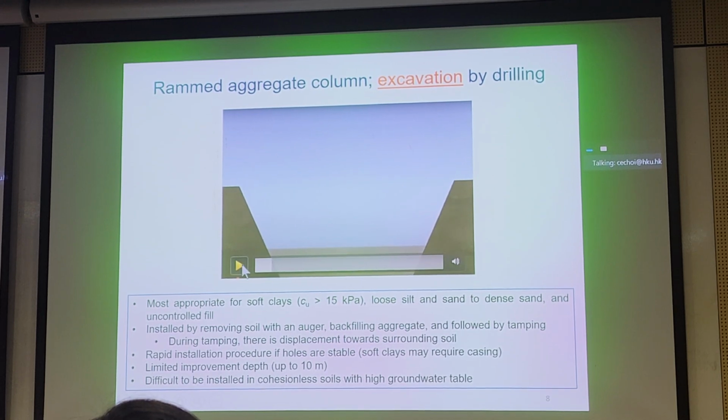And this video is obviously from some expert or a professional contractor specializing in deep replacement, so that's why they're advocating the use of deep replacement, particularly their rammed aggregate columns. So replacing it with stronger material and then compacting the better material to support the footing.